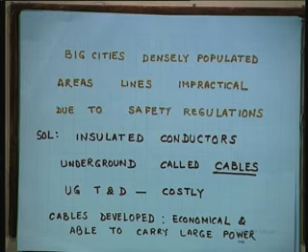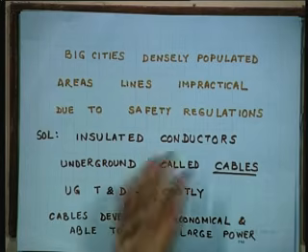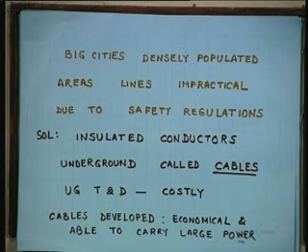And safety regulations also force you not to have a transmission line. There should be 3 feet away from your house. You can't, otherwise children will touch the live wires. So, there are certain safety regulations, how far they should be from a railway track, how far they should be from living buildings or any other construction or structure. All these things you can read in the electricity rules.